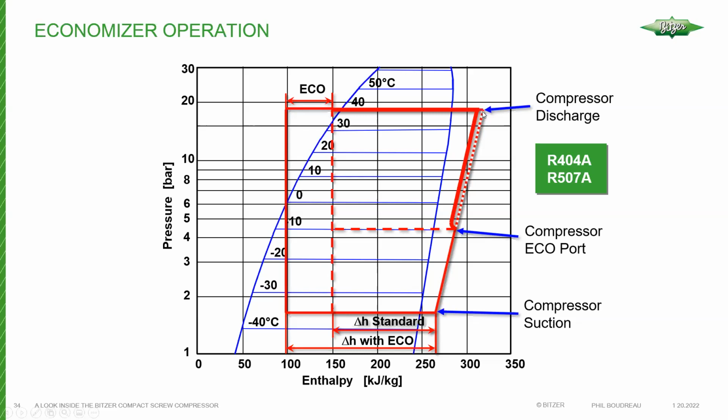So in this particular case, if we were to introduce a second heat exchanger, or I guess a third, if you consider the evaporator and the condenser, we've got an economizer type heat exchanger. Basically, we just call it a subcooler because that's what it is. On one side, it's refrigerating expanded liquid, and that absorbs heat from your main stream of liquid going into the evaporator.